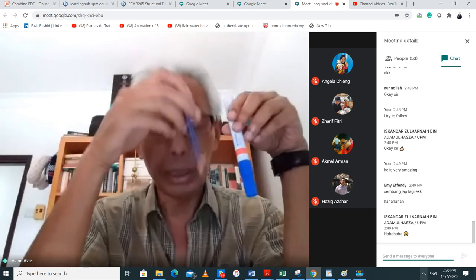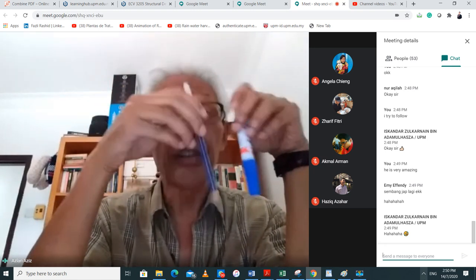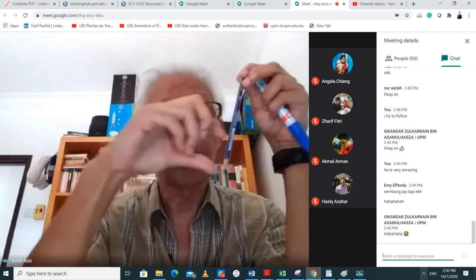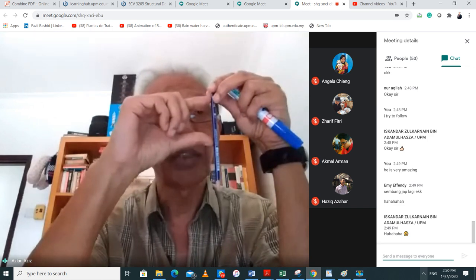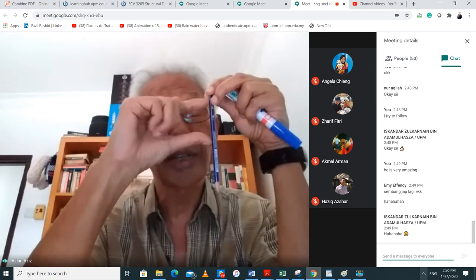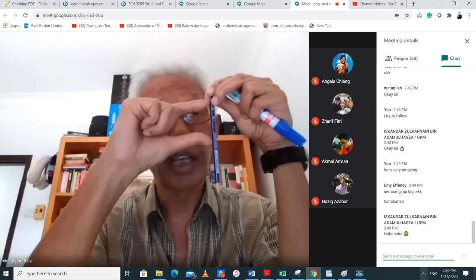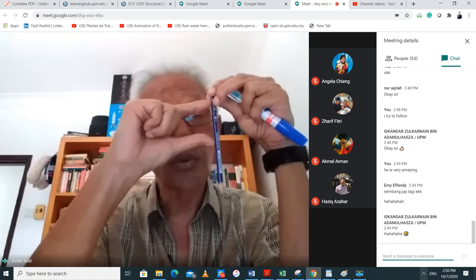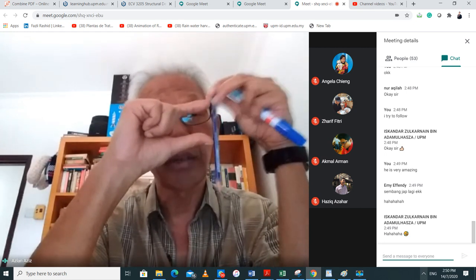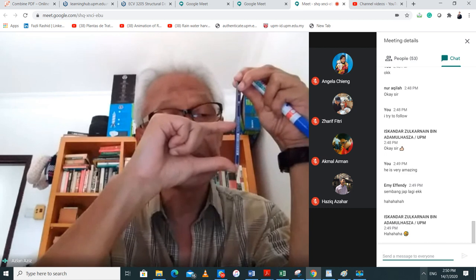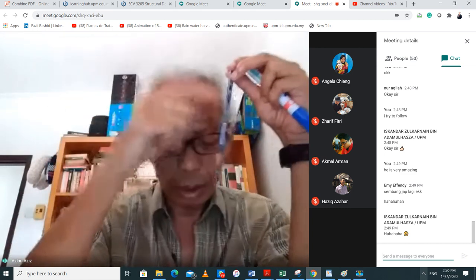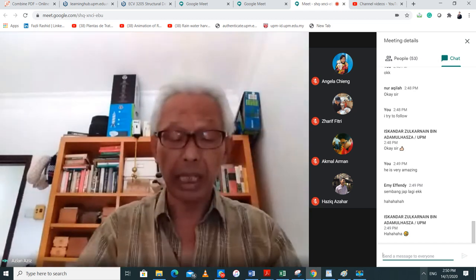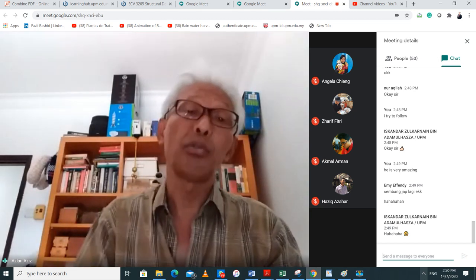So from the Q sub C, we take the average value in the loose soil and also in the dense soil. There are two different values, because these are two different layers, right? The average value in the loose soil, then you divide it by 200. Then you take the average value in the dense soil, and then you divide it by 200. So that's how you get that 10 and 38 in the loose sand and the dense sand.